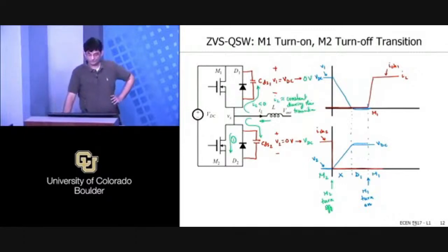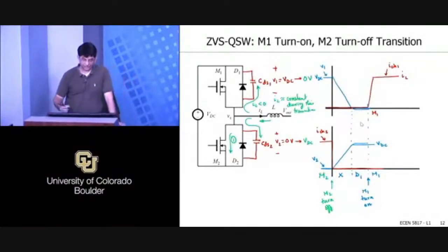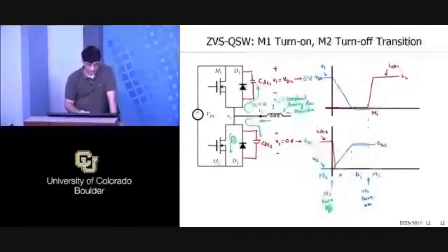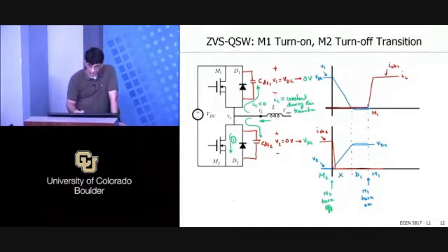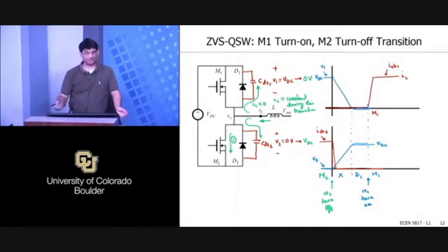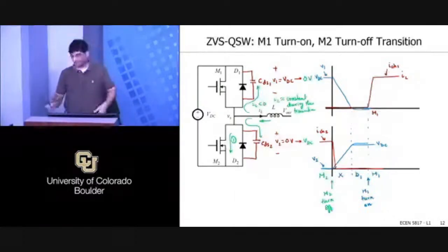Will there be any small power loss because of the diode conducting? Yeah, so there will be some small diode loss there, and if you wanted to be really accurate, this would not come down like that, it would actually come down like that, and the voltage waveform here would actually kind of have this quadratic period and then the linear rise period, right? The same thing we did earlier. I did it much more carefully here.